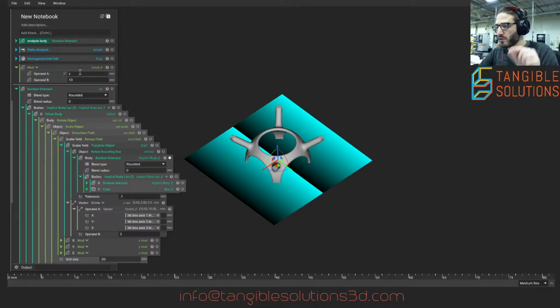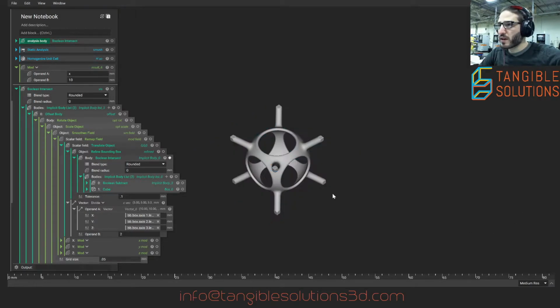But what it does, and we went over this in the last video, so I'd encourage you to watch that if you want to know more about the concept, is that in a sequential pattern we go from 0 to 10, and then, atypically, since most signed distance fields are continuous, you see here we have a break where we go directly from 10 to 0. The good thing is that this allows us to pattern within the space. The bad thing is that if you do not control your cell properly, you're going to get a lot of discontinuities. When you go from 10 to 0, with this nice asymptote, you're not really going to have a nice continuous-looking field unless you control it the right way, and we're going to go through that.